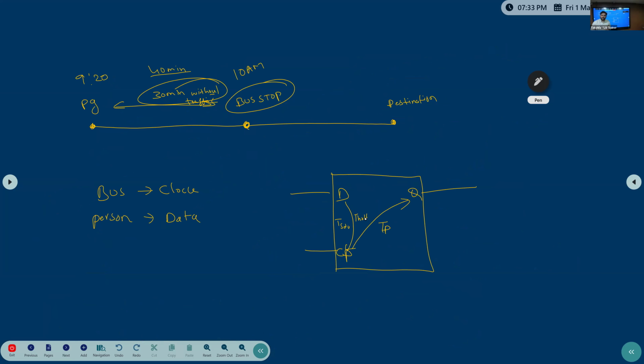We already discussed that a reset pin will be there, a set pin will be there. If reset is also there, reset-related timing arcs will also be there. So these two timing arcs will be there: reset to CP, then CP to Q. CP to Q will be the same, but reset to CP will be there.